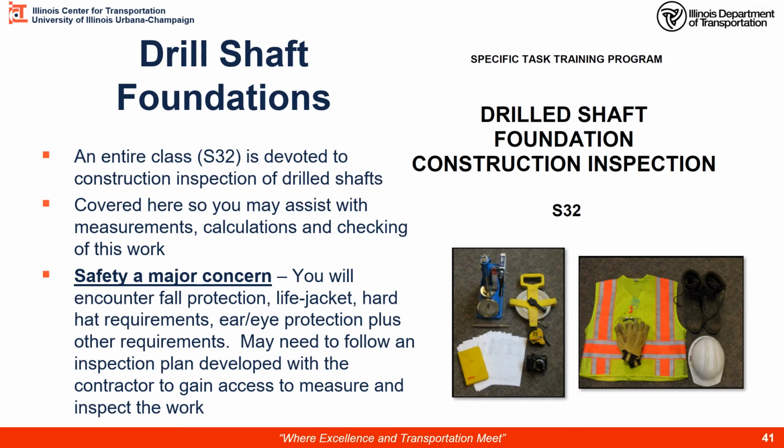The major concern is safety around these shafts. They're basically a deep hole. You may need to utilize fall protection if water is involved, a life jacket, a hard hat, of course, ear and eye protection. Many sites have operational plans of how to gain access near the shaft, so you need to check in with the contractor and resident to make sure that you are following the plan while being positioned around these shafts for measurements and such.